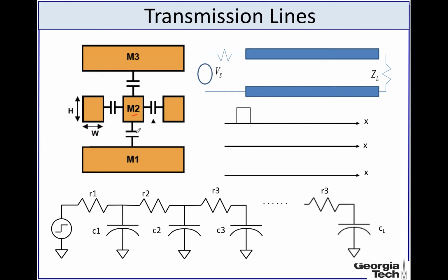The important thing to note here is that this resistance and capacitance are distributed, meaning that if you want to create a model of this interconnect, it will essentially look like an RC network like this. You have resistance, capacitance, and one section that looks like this, and this is repeated many times as you go from one end to the other.